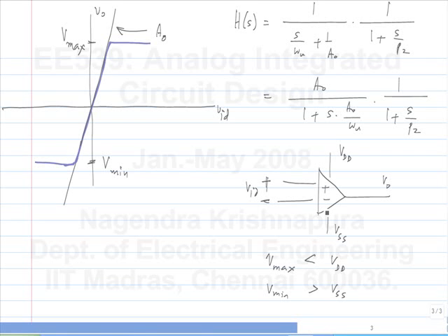Now, what did you say? I didn't hear. Okay, so what is the voltage applied with respect to ground? Yeah, it can be anything basically, right? So far, we have not even discussed what voltage is going to be at each of these points. So this will be some bias voltage plus half the differential voltage, and this is some other bias voltage minus, the same bias voltage minus half the differential voltage.